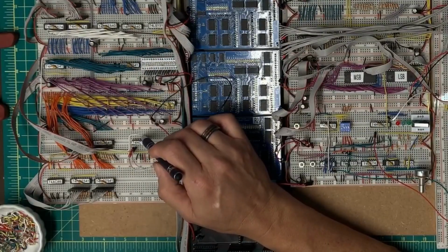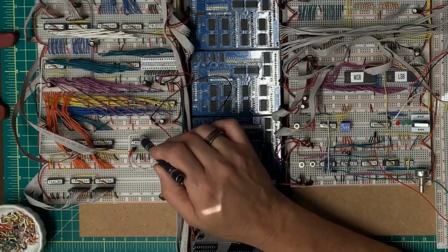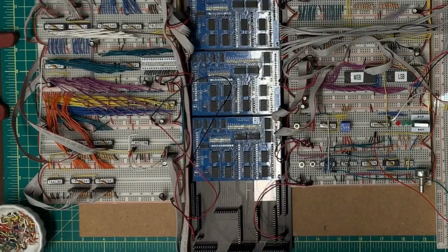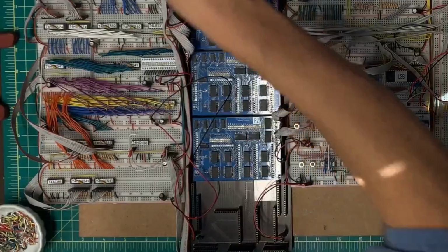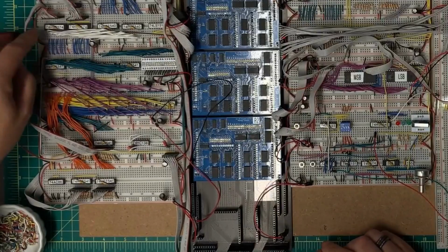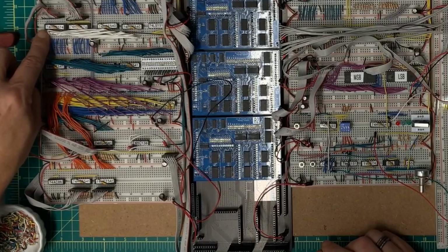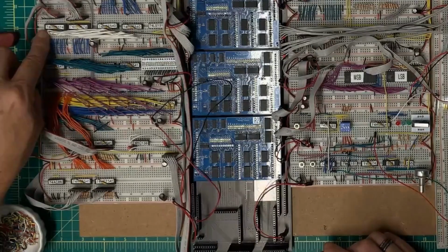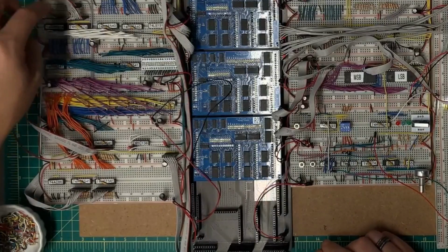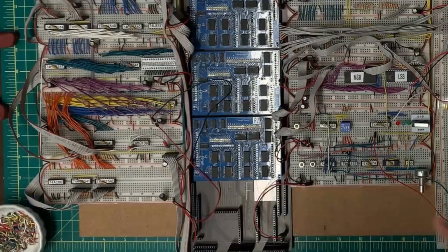And then I've got output 2 and output 3. Both of those are going to be used to drive the other sections of the ALU, the logic unit and the shift unit. This signal is going to be repurposed to be my AND latch signal up here. I need another signal. Actually, I need several more signals if I start talking about the carry flag inputs, which we haven't talked about yet. Okay, I've got 6 here.